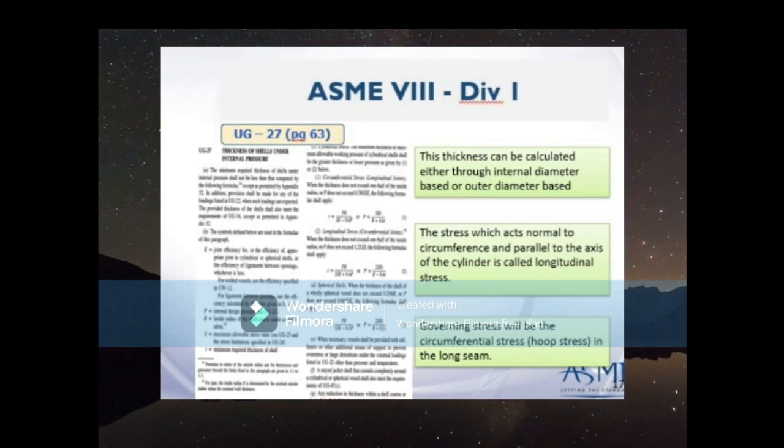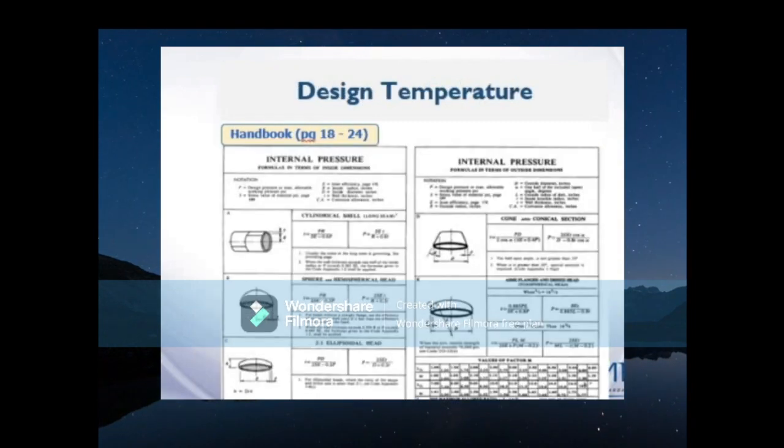ASME Section 8 Division 1. The scope of Division 1, Part UG-27, has been established to identify the components and parameters considered in formulating the rules given in ASME Section 8, Division 1. A simplified equation was developed by the UG-27 ASME Code Section 8 for determining the required thickness of a cylinder subjected to internal pressure. Longitudinal stress can govern the design of a cylindrical section when loadings other than internal pressure induce longitudinal stresses that are greater than 1/2 of the hoop stress due to internal pressure.